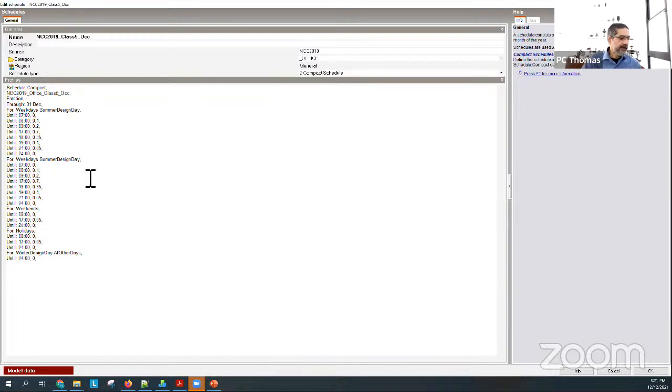I leave the weekday as it is, because what I'm assuming is that on a typical weekday, when I'm trying to predict the energy use, between 9 o'clock and 5 p.m., only 70% of the people are there. And if I remember Mansi's schedule, I think it said 80%. So you can go back and check yours. But for the summer design day, when I'm going to size the air conditioning system, I actually want that to be 1. So I'll do a little trick. I'll double everything.